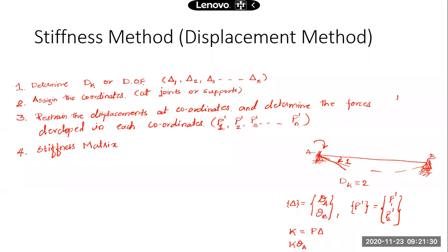Okay, K was expressed as force per unit displacement. So here what I am doing is, I am giving unit displacement, and whatever is the force required for this unit displacement, if I find out that, that itself will be the stiffness coefficient. When delta I becomes 1, K will be equal to P. The stiffness coefficient will be equal to P.